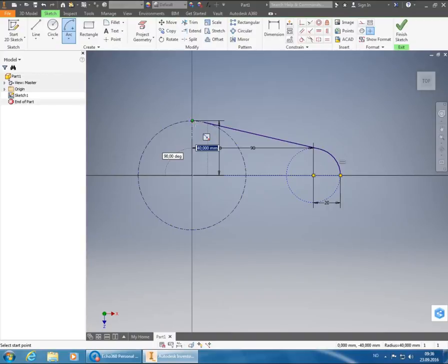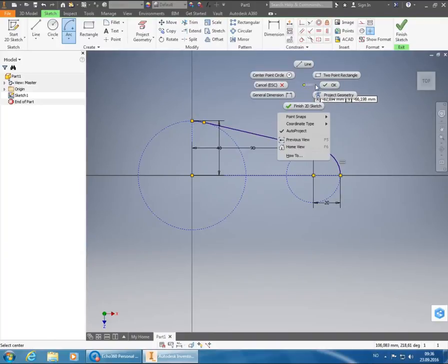So I place the start of my arc there. Then I move it along the circle until it automatically attaches itself to my tangent line there. So I place it there. Now I have 1/4 of the outline of this plate. So I exit the arc function.